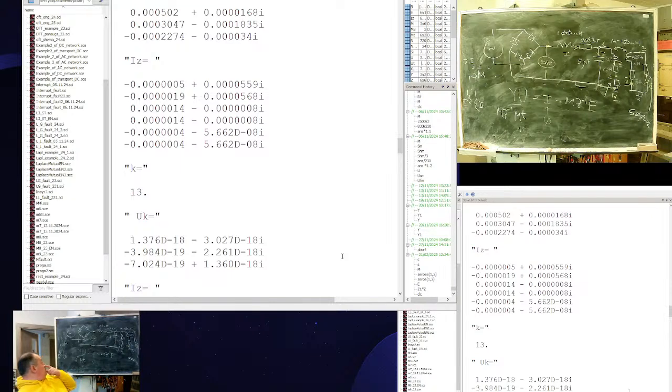See, in DC mode, I should exclude all capacitors, naturally. I should exclude all coils. Of the remainder, I should leave only the active resistance of the winding. It's work I don't like to waste time on. Problem: this will create its own network schematics, its own topology. And I will need to keep a correspondence table of which branch in DC mode corresponds to which branch in AC. I'll do it brutally.